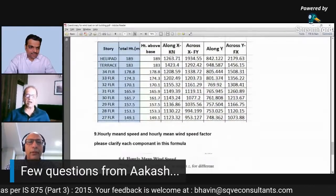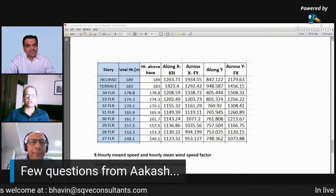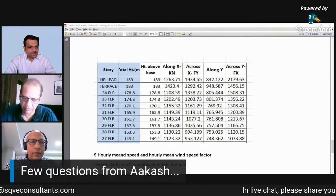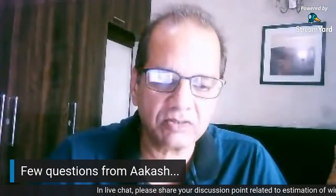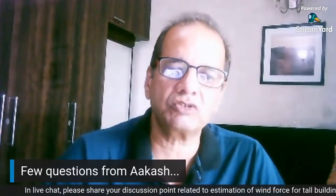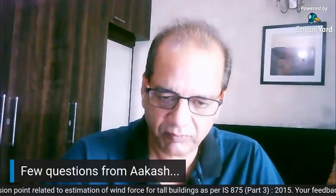In general, along wind response also has a static component, but a crosswind response doesn't have any static component. So, in case of small height buildings, certainly along wind response is going to be larger than the crosswind part. For sure.